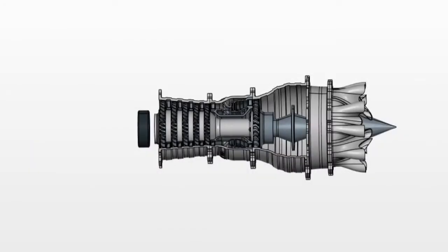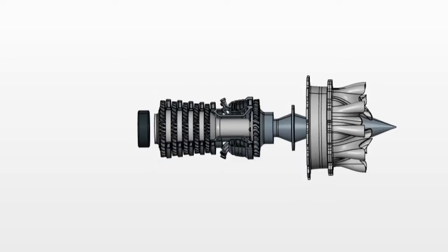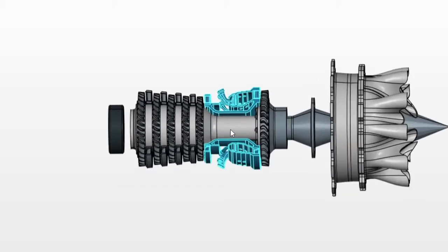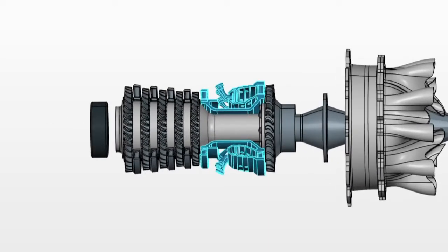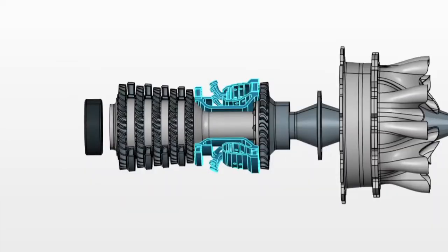The first of the components in the engine is the combustion chamber. By burning an atomized jet fuel, the chamber has the ability to very rapidly heat the incoming air. Raising the temperature of the air will increase its energy and increase the magnitude of the jet propulsion. However, the basic laws of thermodynamics state that to combust the air effectively, the air coming into the combustion chamber must be at a relatively high temperature and pressure already. This is where the compressors come in.